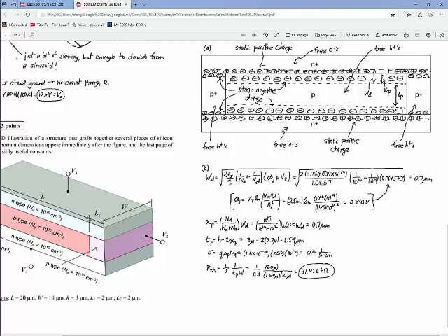But this minus and that minus is not conductive. And so the fact that I have the N plus allows me to create these static charge regions. And if I were to increase the voltage on these N plus regions, that makes the static charge even bigger, right? It makes the depletion region bigger to the point where the amount of P that I have here gets smaller. And so I'm actually controlling the thickness of the slab of P, which then changes the resistance of that, right?